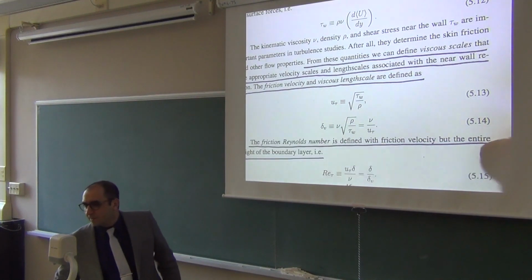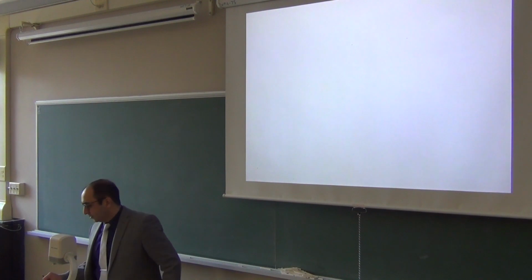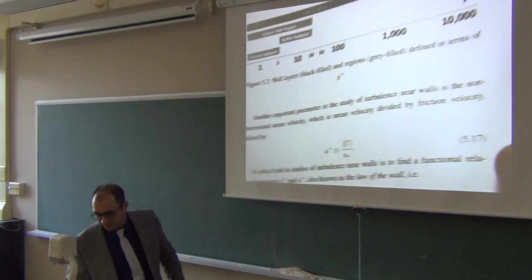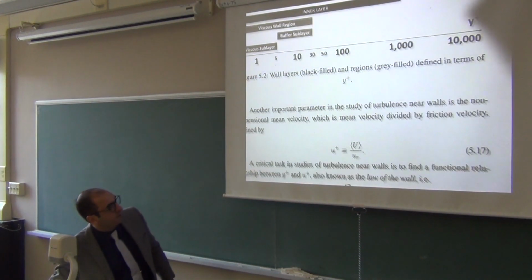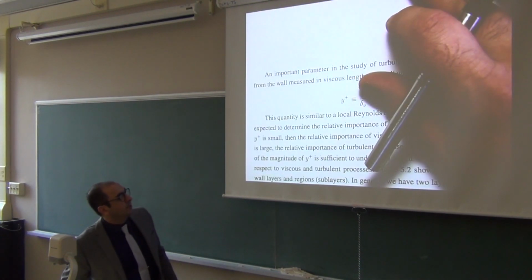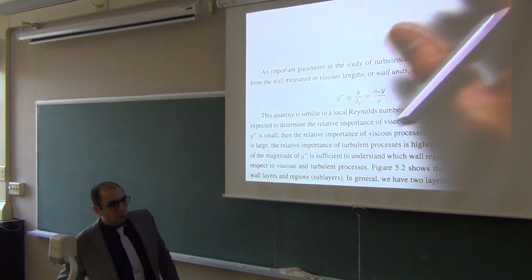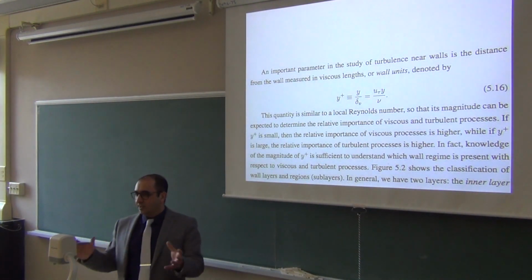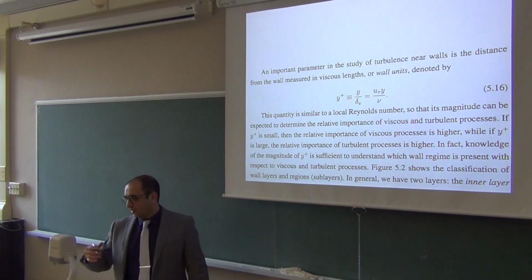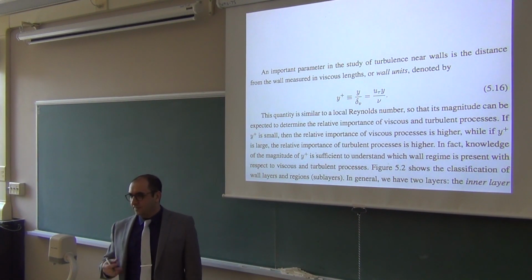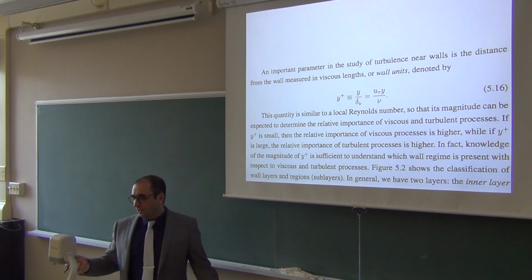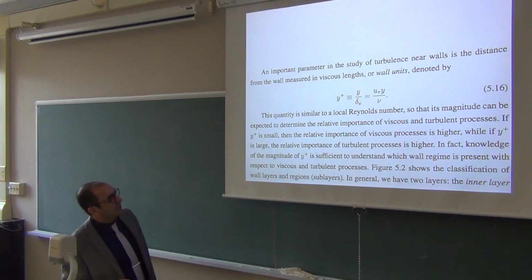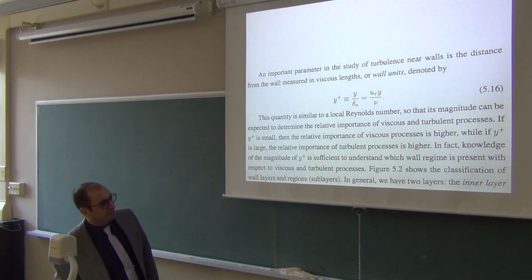Just some more definitions, since some of these other scales pop up and we will use them. This is one way to normalize the analysis of wall flows. Anybody who designs pipes has used the Moody chart. What is a Moody chart? It's a normalized chart to analyze pipe flows, size pipes, and pick roughness factors. As an engineer, you need to normalize and then solve problems. That's the standard way, and we do the same thing with wall flows.